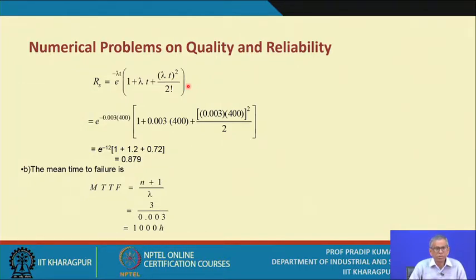That means the system design is such that it ultimately depends on the operation of one component among n plus 1 components. Is it okay? So the extra components you have added, that is n number of components, are added in order to improve the reliability. Many a time it reflects the level of redundancy in the system.